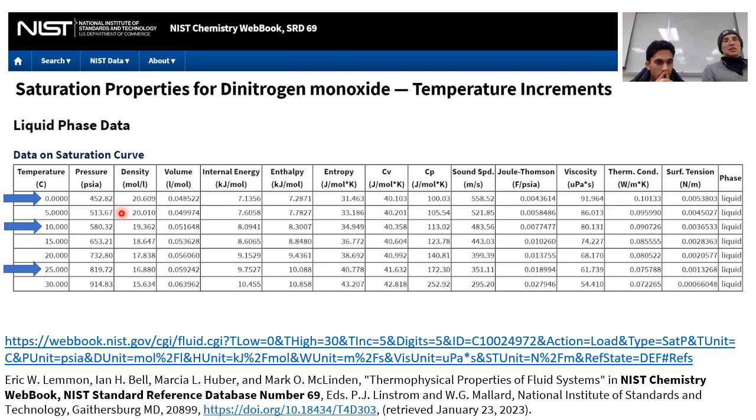I don't say that relative to anything else. One of the main benefits is that we can make it a liquid without going into cryogenic temperatures. So the big benefit is that it's not cryogenic, but we do have to deal with a pretty high pressure that increases quickly as the temperature rises. It's not surprising for the temperature to increase 5 degrees Celsius, for example, but that would increase our pressure 60, 70 psi.